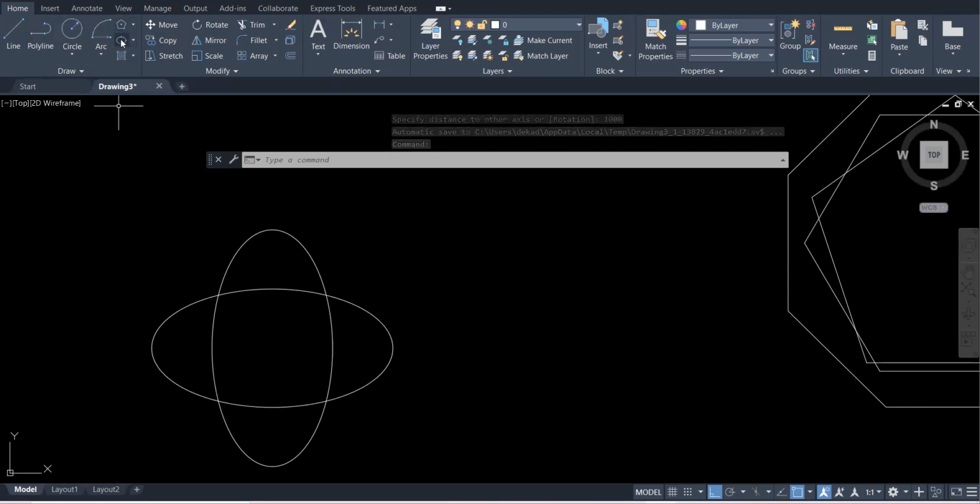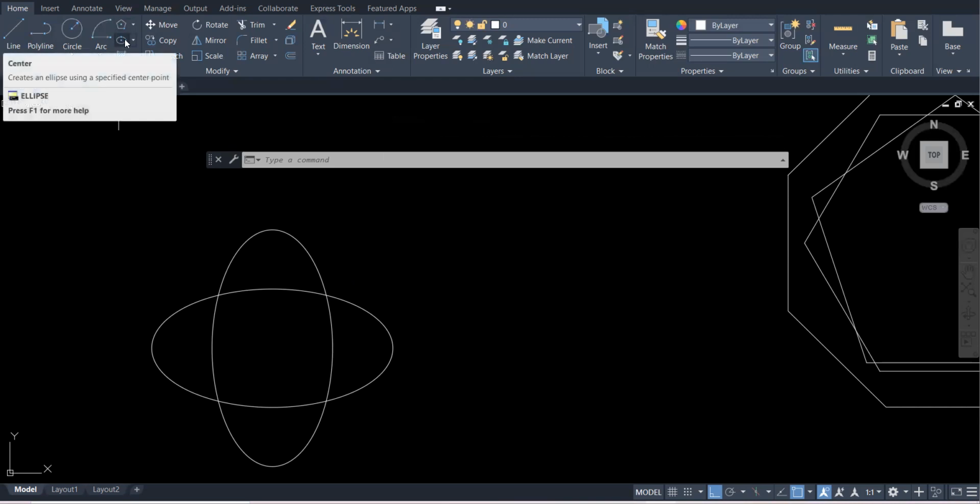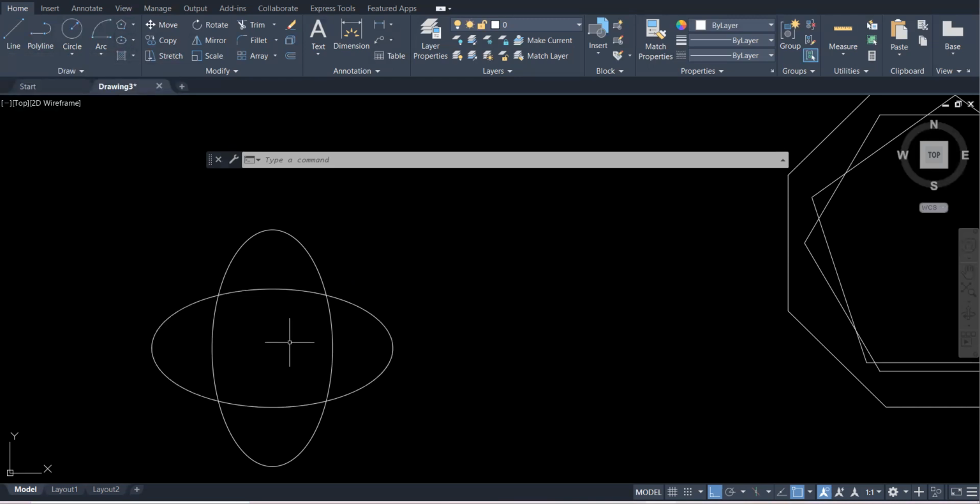All right, so this is a very easy way of creating the ellipse, because you've got two centers, you've got two radii, and just by marking where the center is going to be and marking which radius is going, the first radius is always the x-axis. I just want you to start using the terminology, which is x and y, knowing where your direction is going to be. So I prefer to put the x direction first and the y direction second, because this is the way that AutoCAD prefers information to be input.